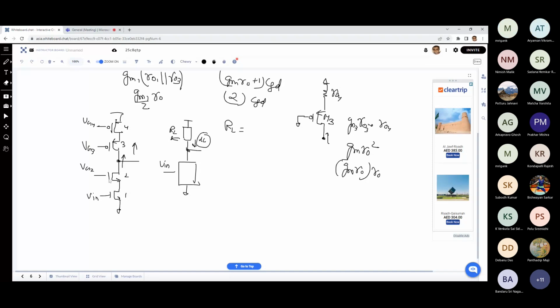So now we also need to see whether this small signal current is going to flow directly. V in is the signal input gate voltage, and because of that you get GM V in small signal current, which is basically flowing out of this MOSFET M1.